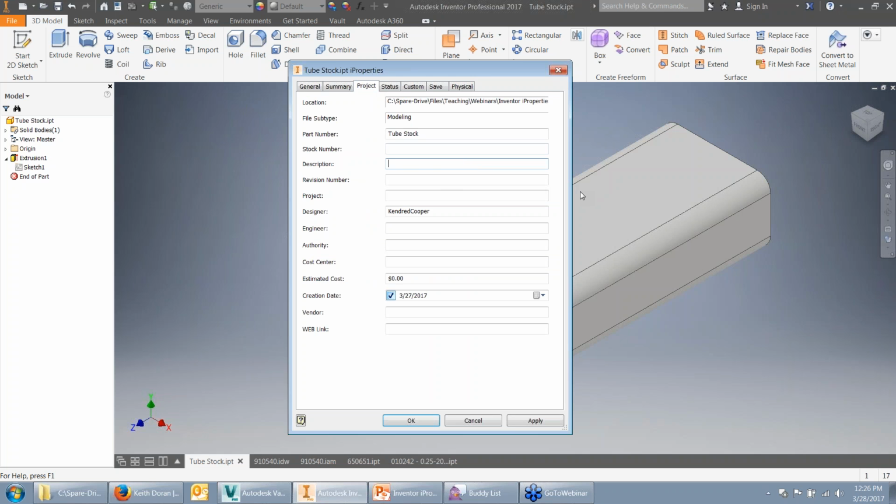And on the description field, we're going to type the equal key, and we're going to use the caret, the greater than, less than symbols. Your parameter names, in order to be referenced in a property field, you have to enclose them in caret. So here's what that means. I'm setting up an equation or a relationship right now using the equal sign. And then I'll use the less than caret, and I'll type in my parameter name.